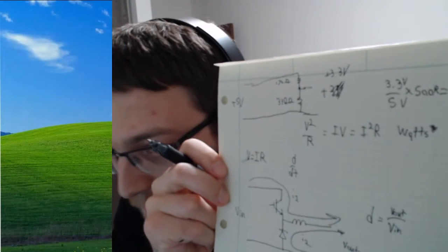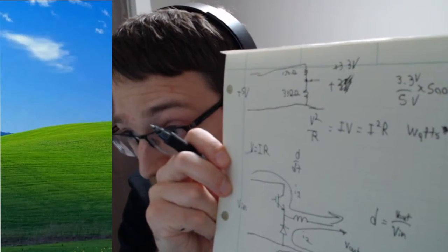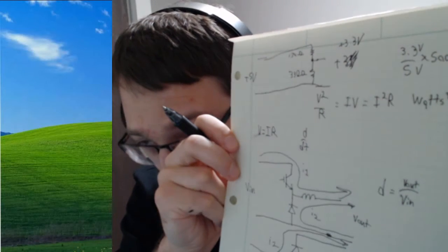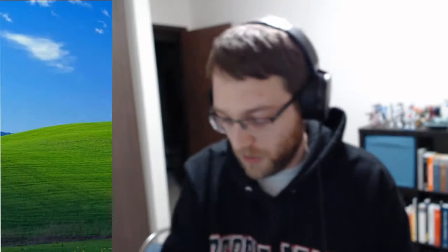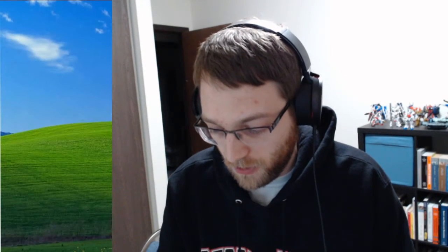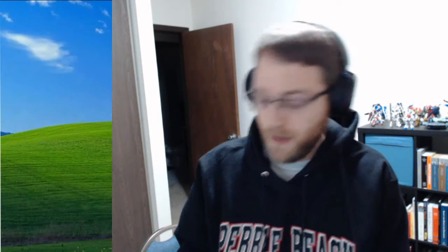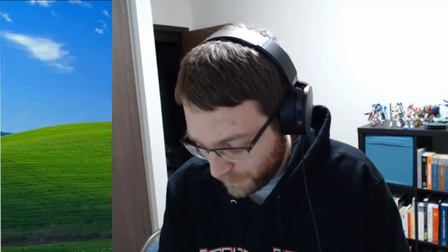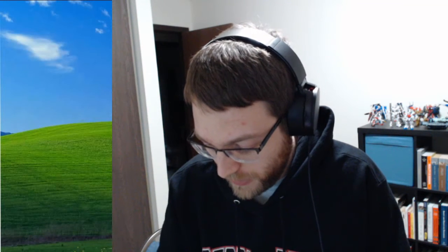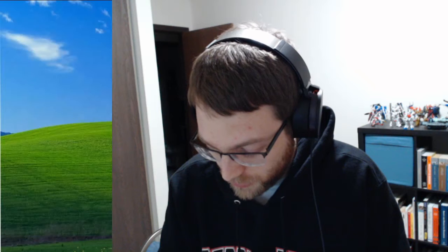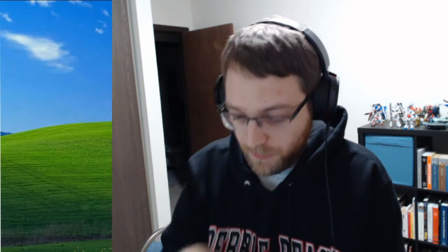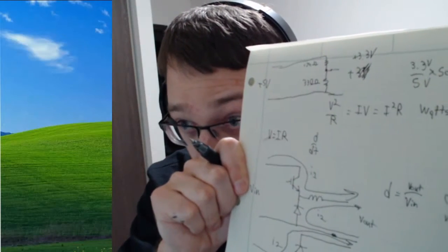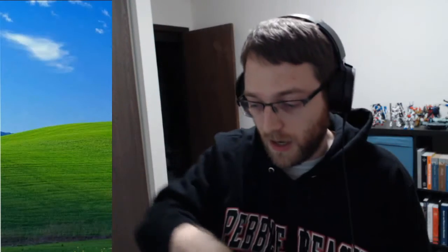But for a buck power converter, you can see that it's just the output voltage over the input voltage. It's really easy to figure out. So in our case of 3.3 volts over 5 volts, that's a little bit north of 66%. D in our standard case would be 66% when Vin equals 5 volts and when Vout equals 3.3 volts. Because, again, this is simple division. It's really easy to figure out.